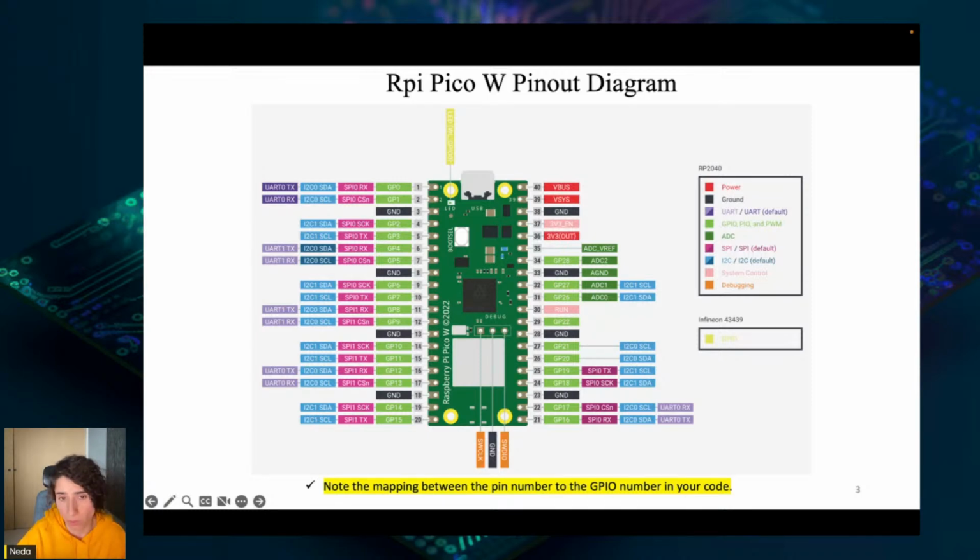And we also mentioned that the resolution of an ADC refers to its ability to accurately represent a range of analog values with a corresponding range of digital values. For example, we had a 10-bit ADC that can represent 1024 different values from 0 to 1023, and an 11-bit ADC that can represent 2048 different values from 0 to 2047, and allows us to capture more detail and provide a more accurate digital representation of the analog signal.